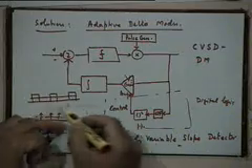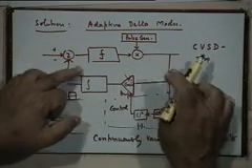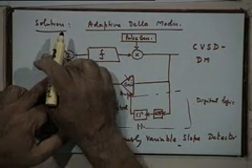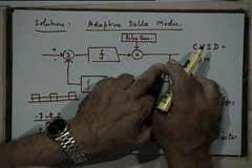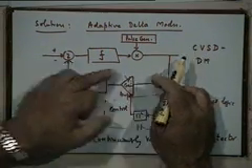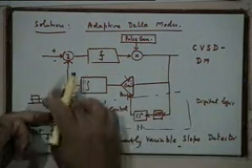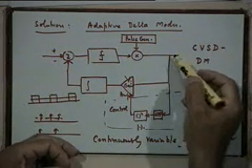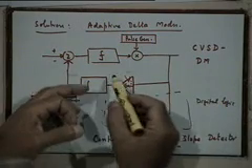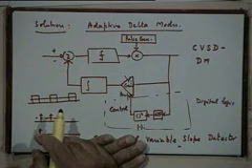Remember, this is also your demodulator, isn't it? Here is this, and this will now approximate the message waveform much better, and this approximation is being derived from the delta modulator output. So your feedback part, whatever it is, also becomes a delta demodulator. Your demodulator circuit now becomes this. So did you get the answer to your question? That is why we would rather derive this information from the delta modulator itself, so that whatever I am doing here becomes my model for what I should do at the demodulator. Is that clear? It's a good question that you asked, and the answer is this.